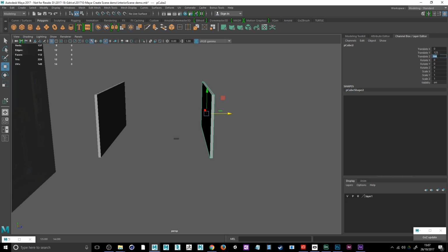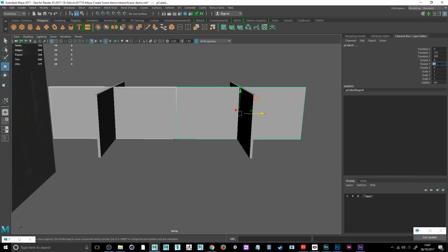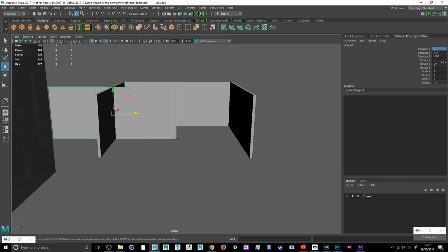but I am able to move these around into this square. So that can translate here, 300, and if I duplicate both of these, what I need to do is rotate around the y-axis, and then individually I would change that translation Z and push it back in the other dimension, just to make this 4 walls for my piece. So I'll take that from there, translate Y 300, minus 300.